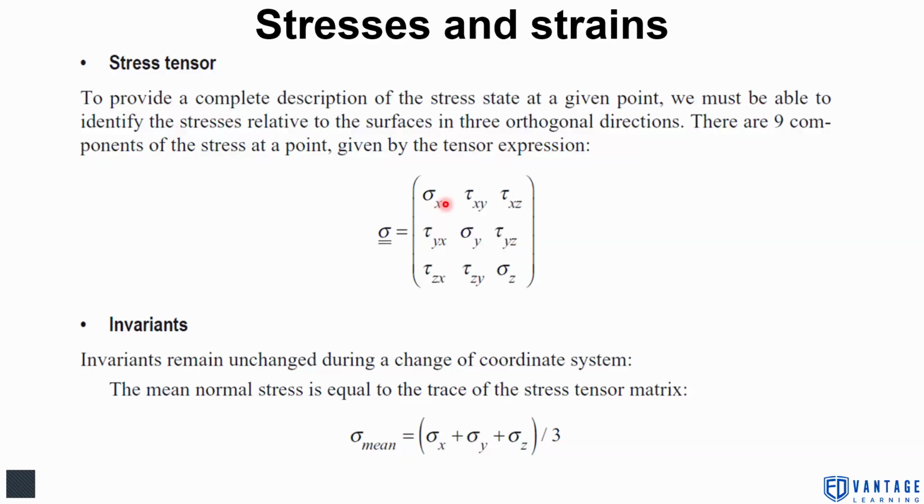orthogonal directions. So if I'm applying stress on the x direction or x plane, let's draw another body here, a cylindrical body. Applying compressional stress from both sides on the area, with a force and of course an area of cross section. This stress application in the x direction, only on one axis, might generate shear stress in two other directions, xy and xz. So you can see this normal stress and its corresponding shear stresses, tau xy and tau xz, where my application will be on the x-axis, but my failure will be on the y-axis, as displacement or disarrangement, right?